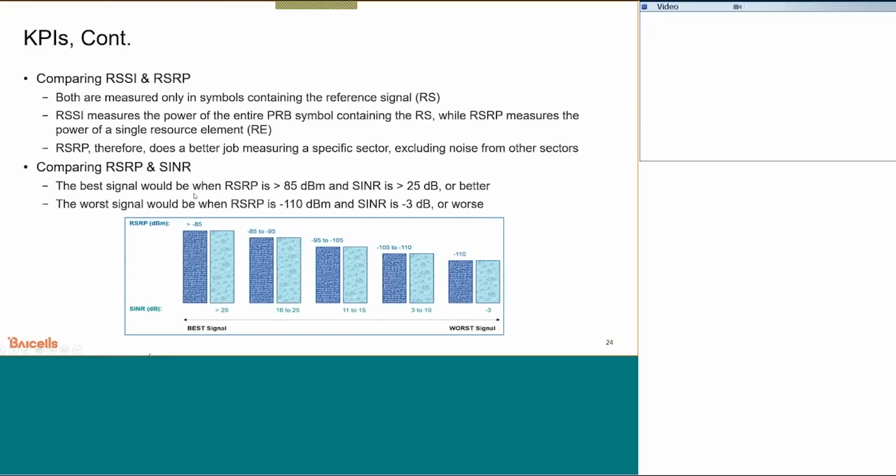Now, just as I mentioned earlier, these are what we would consider good signal, but technically from an operator standpoint, I generally shoot for better than minus 85 dBm, and like I said, SNIR or CNIR in the teens, you should expect decent performance out of them.